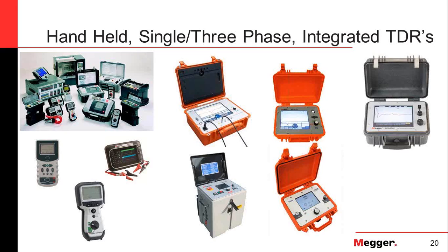Okay. And what is the approximate length of a cable that the TDR can send a pulse down? Typical TDR lengths would be like 25,000 feet maximum, 80,000 feet maximum. We have some specialty TDRs that can see farther than that. It's not very common to have a cable that's too long for your TDR to see to the end of it.